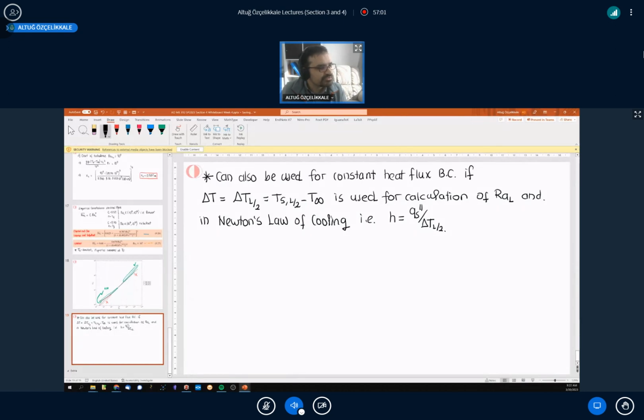And what becomes important here under those applications is the temperature operating conditions. So is there a limiting temperature? Like there's going to be hot spots on the surface, like there's going to be a location where the temperature is going to be greatest. Which location is that going to be? It's actually going to be the location where the boundary layer is the thickest, and it's going to be the trailing edge of the plate, if any. Or you can be interested in what's going to be the surface temperature of the plate at any location. Therefore, it is interesting that we can actually look into that. So this is an interesting quantity.